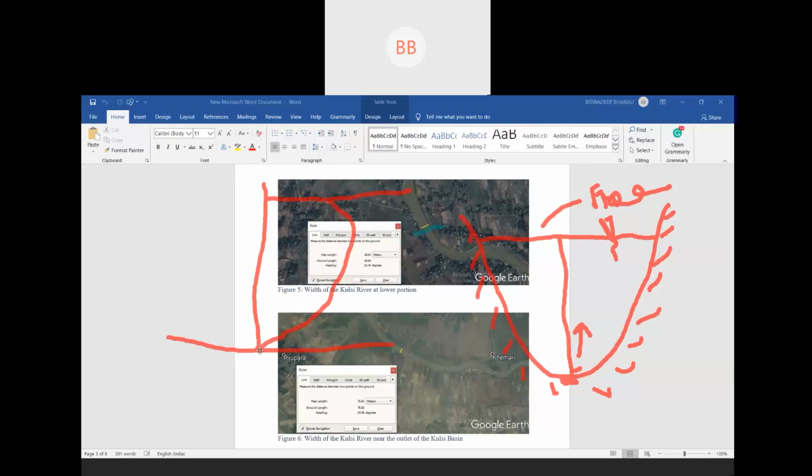We consider the velocity at the bottom is zero, though it is not zero, but theoretically we consider it zero. Then when you go upward, if this is your y value, the depth of flow from the bottom of the channel, your velocity increases, and when it reaches the surface, due to the interaction between the flow of water and the flow of air, your velocity is again reduced a bit.